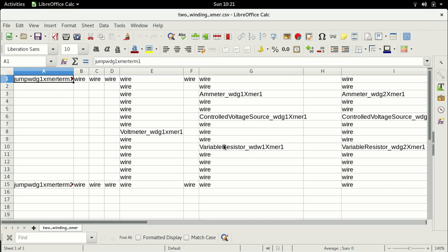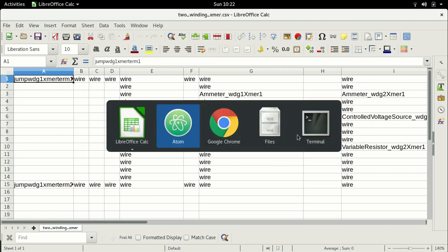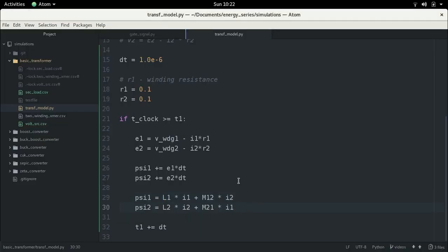Now besides that, the winding usually has some amount of leakage as well, because not all the flux that is produced by the winding is linked with the core and made available to the other winding. Some amount of the flux will also leak. So this winding will have to consider the magnetizing inductance and the leakage inductance. That will be the self-inductance of this winding, right? Whereas the mutual inductance is just the magnetizing inductance. So let me go back to the control file and start talking about this.